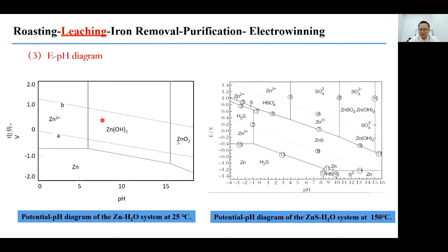If we have some zinc sulfide in the solution, it can also convert with reaction 1 with some oxidation, and we can get zinc ions and sulfur, or with reaction 6, zinc ions and sulfate ions. This is also used in direct leaching with reaction 1 in the atmospheric pressure leaching, and also the oxygen pressure leaching developed by Canadian companies.